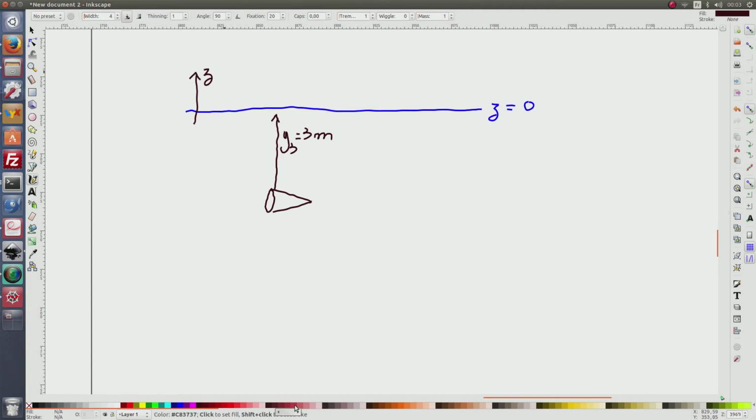And I assume that I want to go, for instance, here, for the robot, at the depth y3, which corresponds to 2 meters. So in this situation, I will have the error y3 minus y3 bar, which corresponds, in this case, to 3 minus 2, which is equal to 1, which is positive. And in this situation, I have to go upward.